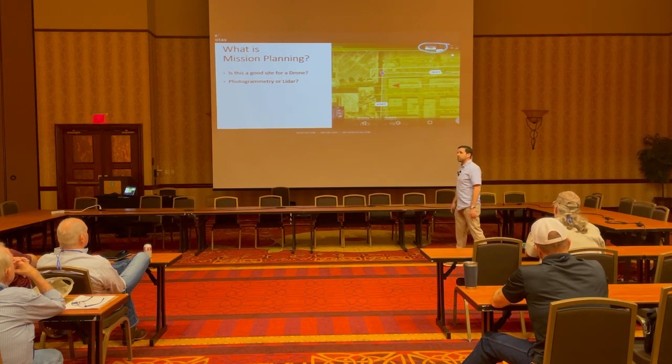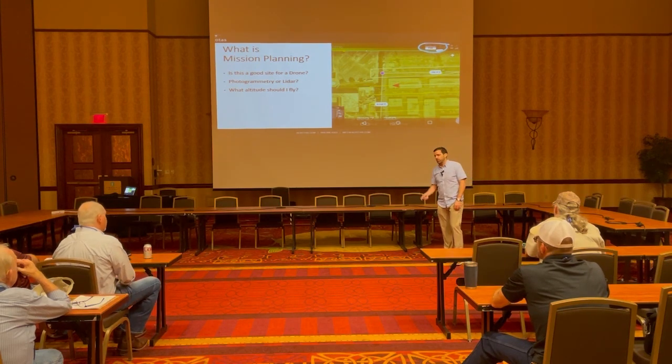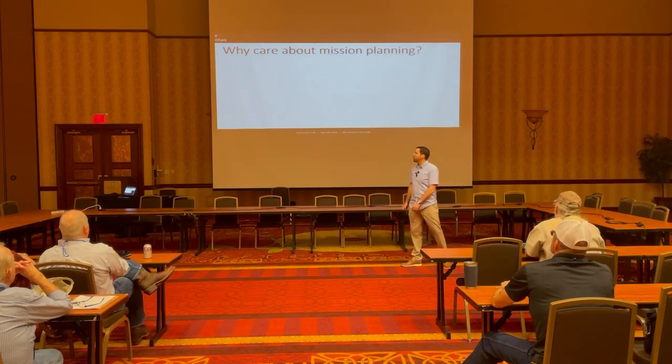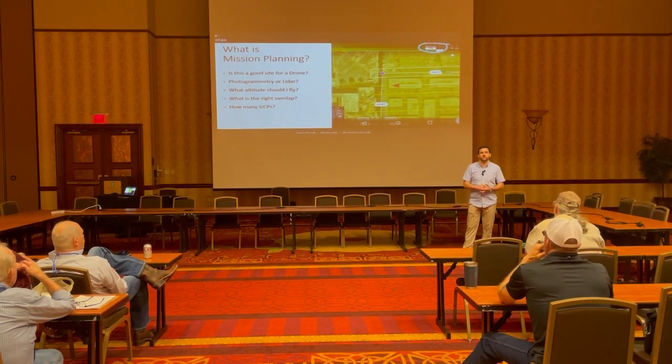Asking yourself photogrammetry or LiDAR, pretty simple question. I kind of already covered some of that. What altitude should I fly at? There's a trickier one that I'm going to cover in a second. What's the right overlap? How many ground control points should I set? How many targets? These are some of the questions that you should ask yourself in mission planning.